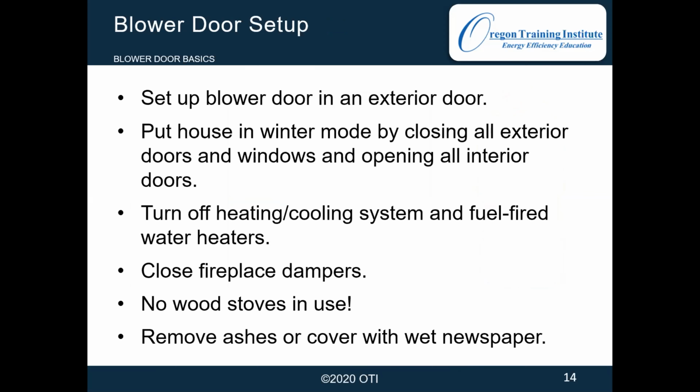So we're going to need the house set up to do a blower door test. And normally with the blower door, we're depressurizing, sucking the air out of the house. So we'll need to ensure there's no fires going, and any wood burning appliance needs to be fully buttoned up where the ashes don't pose a risk of coming out and getting sucked into our blower door, as that's going to make a really big mess and can ruin the carpet and the furniture.